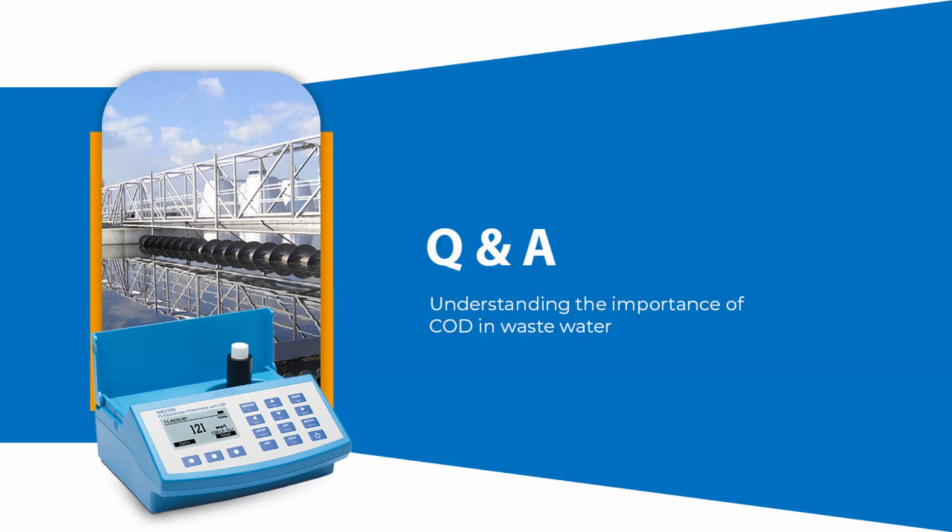Basically, a high level of COD means the wastewater contains too much organic material, which can reduce the level of DO in the water. So the effluent is discharged, harming the local environment. This is caused by the accumulation of solid waste, soluble organic compounds, residual food waste, emulsion oils, and dying bacterial cells responsible for the decomposition and the release of DOC, dissolved organic carbon, in the wastewater, which in turn increases the COD. Thank you very much, sir.